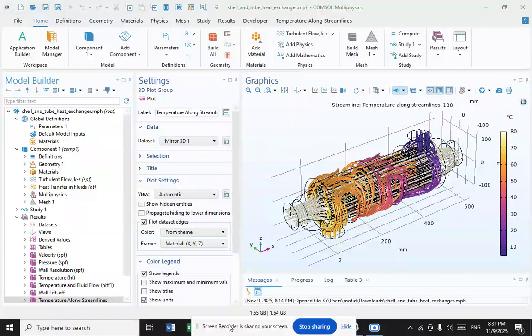Typically, the ends of each tube are connected to plenums, sometimes called water boxes, through holes in the tube sheets. The tubes may be straight or bent in the shape of a U, called U-tubes. Tube diameter. Using a small tube diameter makes the heat exchangers both economical and compact.